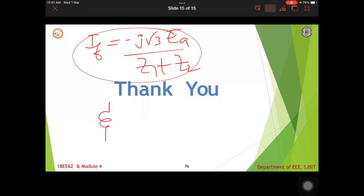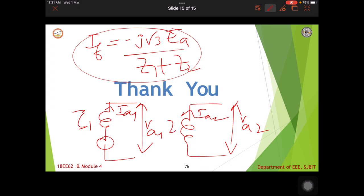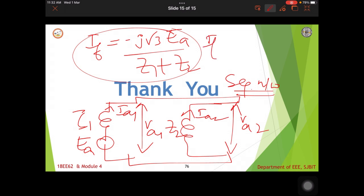The sequence network is very simple. The positive sequence network and negative sequence network are connected in parallel. This is IA1, this is IA2, this is VA1, the voltage across the terminals, and VA2, and this is Z1, this is Z2, and this is EA. They are connected in parallel. This is the sequence network, and this is the fault current IF. So easily you can find the fault current and the sequence network from the initial calculations.